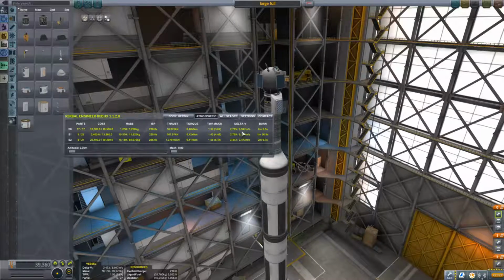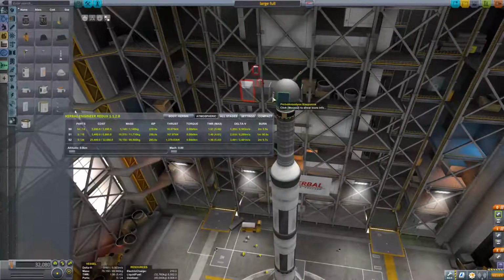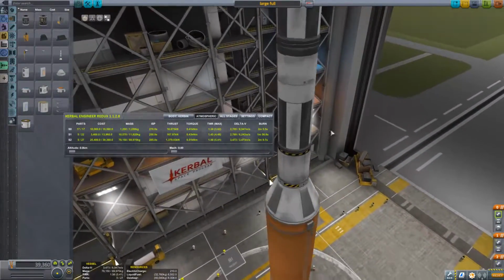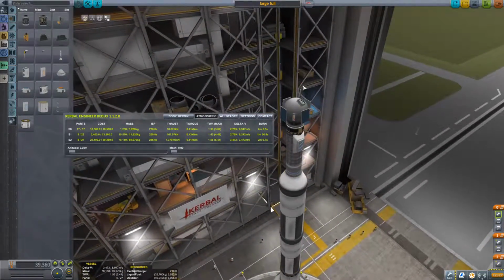So we've reduced this down to less than 9 kilometers per second of delta V, because we weighed down this upper stage even more. The lower stage, I think, was at like 3.7 kilometers per second in our estimate. Adding these different parts, no, the 3.7 was definitely with it being in space, not adding these parts. So we didn't really reduce the total delta V of this bottom stage a whole lot, because relative weight, adding a few little things up here doesn't matter.